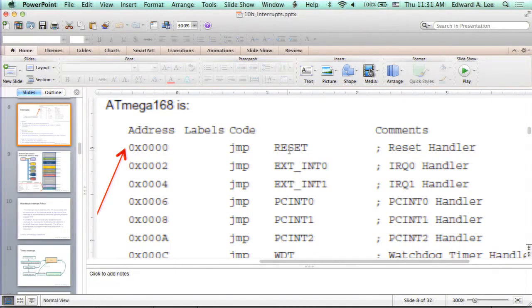Yeah, so you can't actually put your reset code anywhere you want in the memory space because you've only got so many bits for address. You have to specify an offset address. And, typically what will happen is in the architecture design, it tries to encode the jump instruction with very few bits. Okay, so maybe the jump instruction is specified just by the first 3 bits of the address, leaving you 13 bits to specify an address, but that limits where you can put the interrupt service routine, et cetera, right?